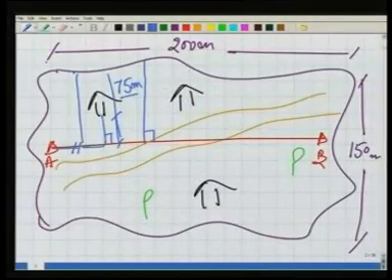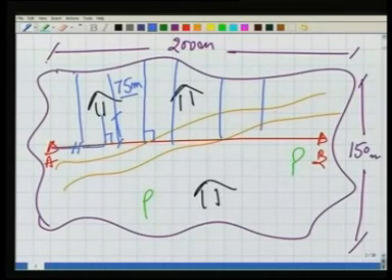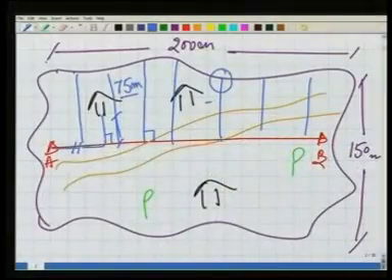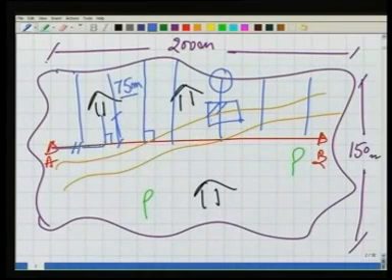Or otherwise also, measuring this entire boundary, taking so many offsets of the order of 75 meter, it's not advisable. Here in this case, maybe you can measure the distances, but there might be some cases where you cannot measure the distance. You want to take the offset to this point, but there is a building here. We cannot take this offset. So we cannot really make the map like this.